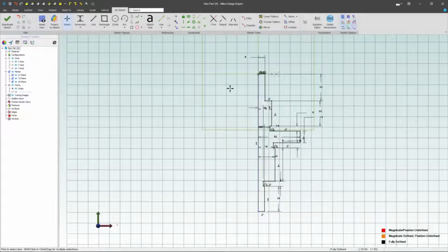But if you're actually going to manufacture the part, it may be worth noting that if this dimension were to have a tolerance of, say, plus or minus 1, and then the next one has a tolerance of plus or minus 1, and then the next one has a tolerance of plus or minus 1, then if this is plus 1, and this is plus 1, and this is plus 1, you have a stack up of tolerances that will be plus or minus 3 when you get to some edges, because every single edge can grow or shrink by, in our arbitrary case, 1.